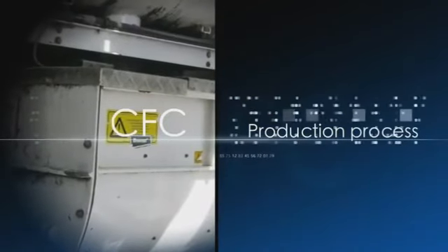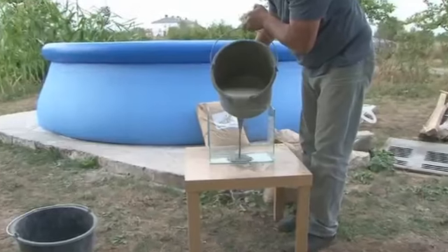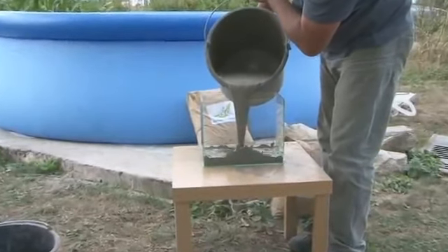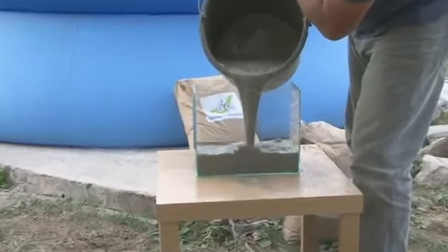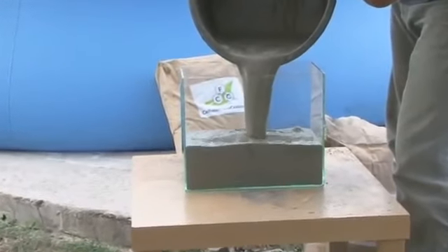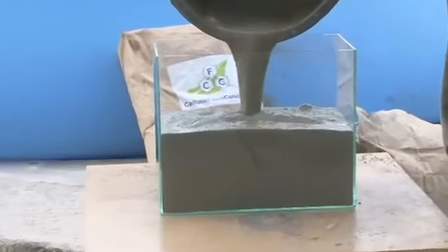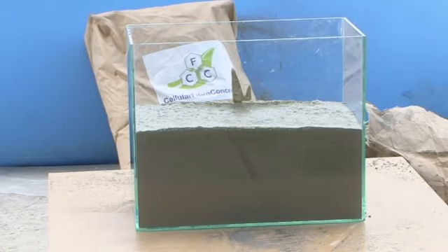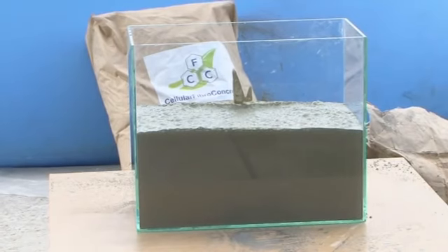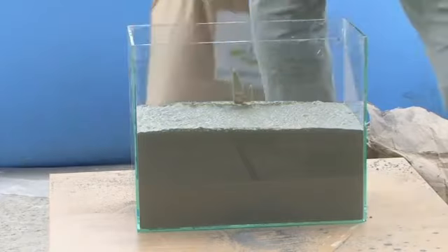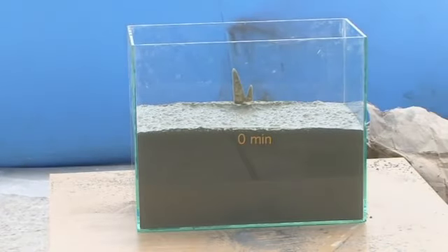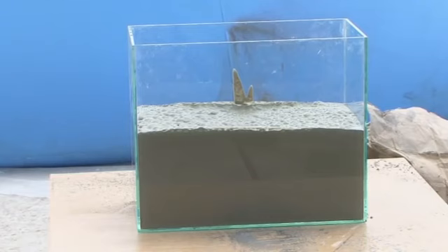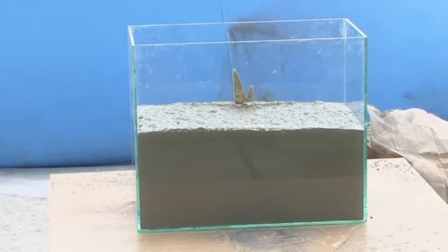Production process. For the production of foam concrete are mechanically mixed cement, filler, and prepared in advance stable foam. The difference in the preparation of foam concrete and gas concrete is that the latter is produced with the help of a chemical reaction, which generates hydrogen bubbles, creating many tiny spherical cells in the limestone, cement, sand mixture. Mixing of the components with water produces aerated cellular concrete with density varying from 250 to 1,400 kilograms per cubic meter.